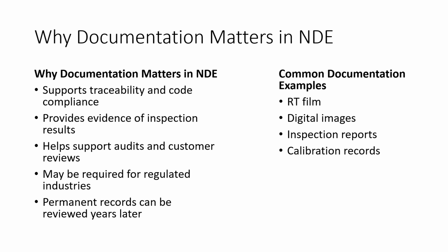Why documentation matters? Why do we document this stuff in NDE? Well, traceability and code compliance, depending on what we're building, depending on how important it is. We probably want to have some kind of traceability. Big bridges over rivers, that if something goes wrong, somebody's going for a swim or whatever, it's going to provide evidence that inspection happened. Hey, Fred looked at this, signed off. Fred was a level 2. We looked at it. Here's our paperwork that says this happened. And then if audits or a customer review, hey, did you guys actually do this?